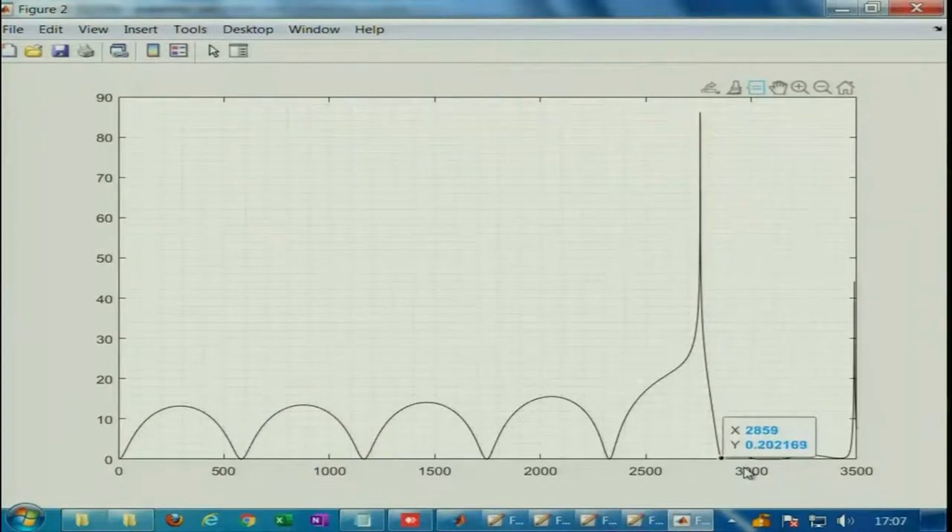So, what it means is that beyond 2814 hertz this will definitely fail, and that is what is happening. Just a little after that we are getting a complete collapse of the dome and trough feature, and before it collapses it gives you a massive peak, just a bit before 2758 hertz. After that there is a complete collapse, and as you can see you get a very spiky characteristic with a number of peaks.